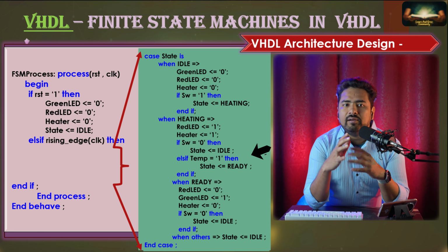Environmental things can be temperature, humidity, etc., which can also trigger some random state. And from that state, if it is not meeting any condition to select the next state, or your product is not even doing its operation, then issues can be anything. So in such events, the when others condition covers everything for you.